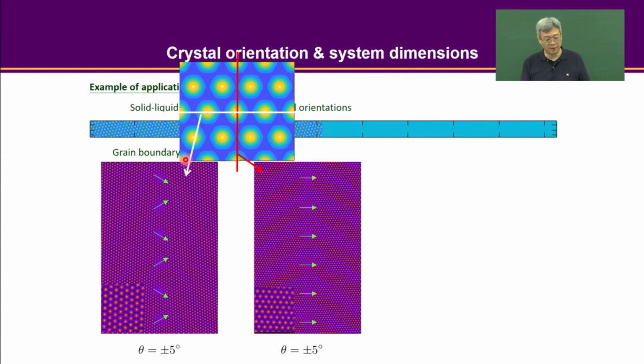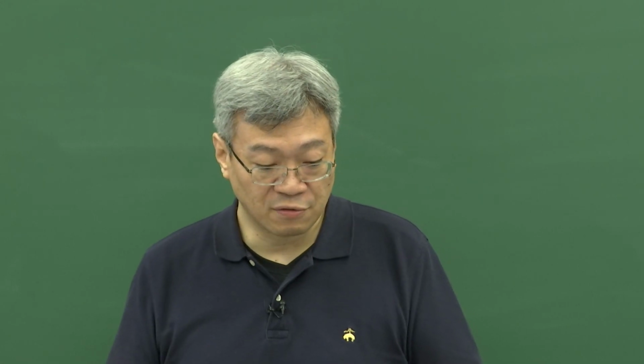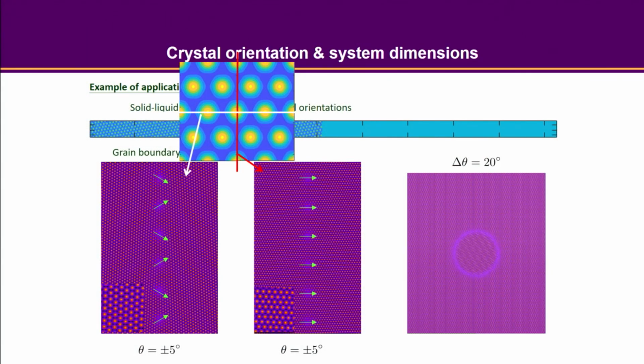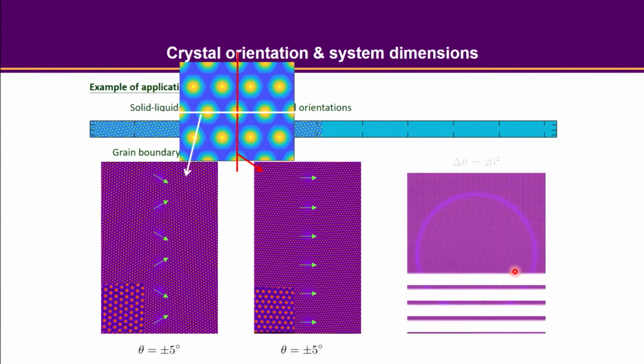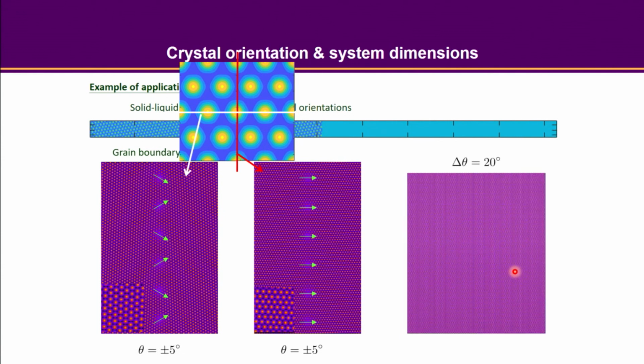Okay, so with the knowledge from before of how to set up a stress-free PFC simulation, you can already carry out the grain boundary calculation. And because you also know how to set up misorientation, you can start with a single crystal and, for a certain area of your triangle lattice, cut a circle and rotate the center grain by, in this case, 20 degrees, and let the grain relax. So you are starting the grain growth problem.